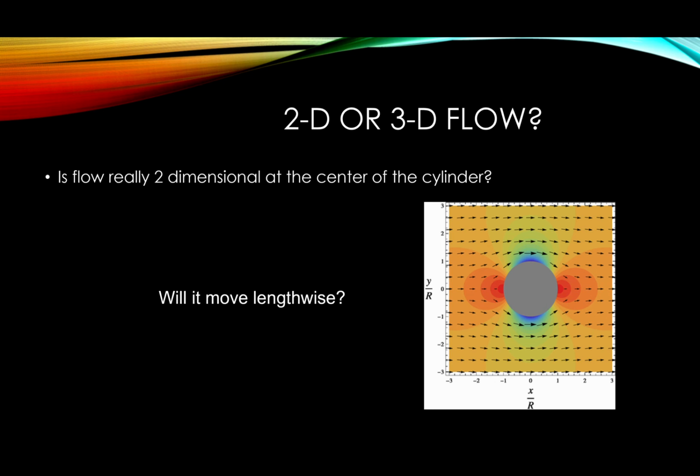Could there be 3D flow at the stagnation point at the center of the cylinder? I think the answer is yes, because at the stagnation point, the flow has no energy, and it'll move the first way it's jostled. So if there's any other force to that, it would be a 3D flow. It seems possible, but since there were very few particles at the stagnation point, it was very hard to visualize one way or the other. And also there are very few 3D visualizations of stagnation.